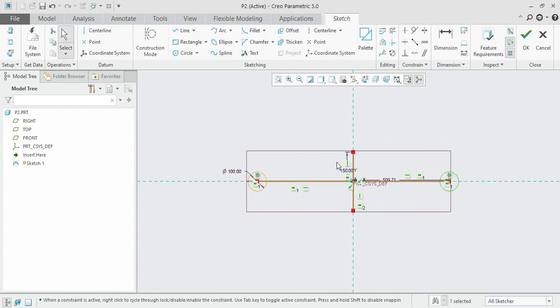Okay, finished. Now we shall draw the upward surfaces for these two horizontal circles. Similarly, click from the vertical line and complete it by placing it over the tangent of the circle. See, the tangent symbol forms. Now follow the same procedure. Place it over the tangent.